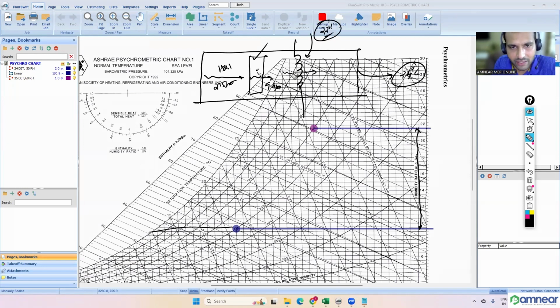But this we have to calculate. When it is leaving, the condition we will be receiving is 24 degrees Celsius. The advantage, since the desiccant wheel is removing the humidity required, is that the coil surface temperature we don't want to keep at something like 13 degrees Celsius. So if you are using a chilled water system, then we don't want to make the chilled water temperature so low. So that is energy efficient. Correct. So that's an advantage for heavy industrial applications and all.